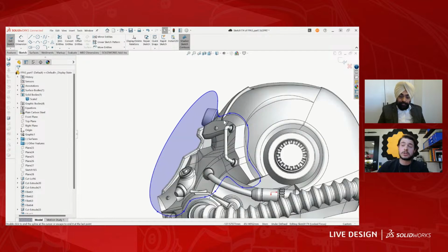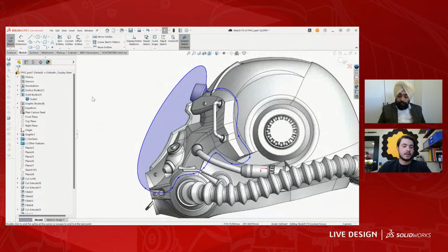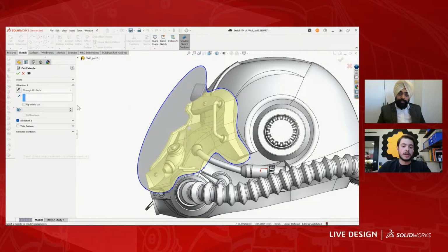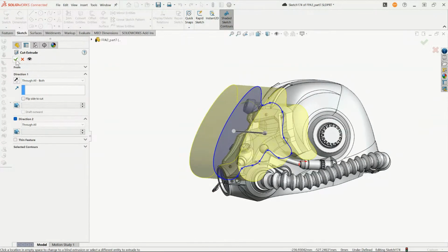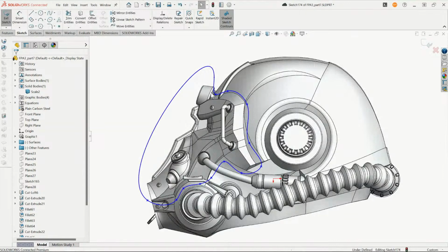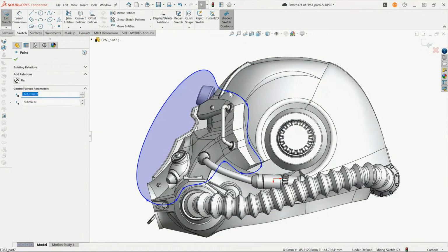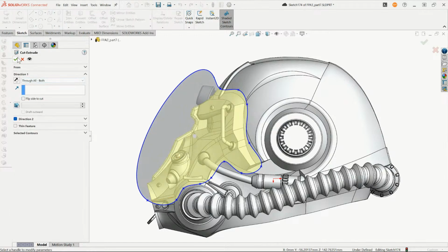And, if I was to do this for the final design, I'd go through and convert all these entities and figure out what lines I actually want to separate from. But in this case, I just did a rough sketch here, and we can see how this will turn out. But now what I'm able to do is do a cut and remove this front section. So we're going to do a cut extrude, remove those from both sections. Now, as I said, special geometry sometimes requires a little bit of extra work. Let's see where it might be clipping through.